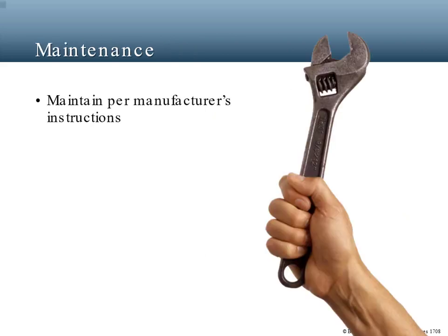Maintenance of equipment is another critical safety issue. Equipment with aerial lifts must be inspected before each work shift. Equipment must be maintained and repaired according to the manufacturer's instructions. Any equipment found not to be in safe operating condition, either during an inspection or during operation, must be immediately removed from service until repairs are made. This includes leaking hydraulics, frayed or cut hydraulic lines, and frayed wires.